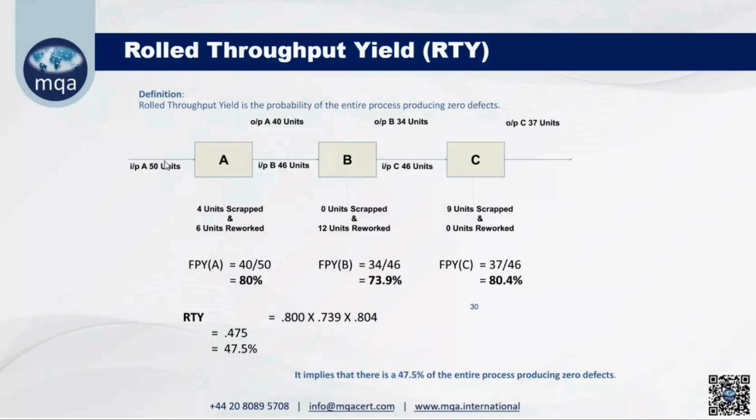Suppose I am manufacturing in machine A. I am giving 50 parts to machine A. Now machine A gives me 4 rejected parts. Scrap means rejected parts. 4 parts are rejected in machining and 6 units are reworked. See, reworked units can be reused, but we consider rework also in yield.